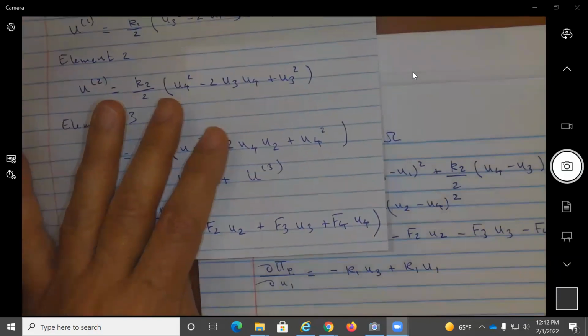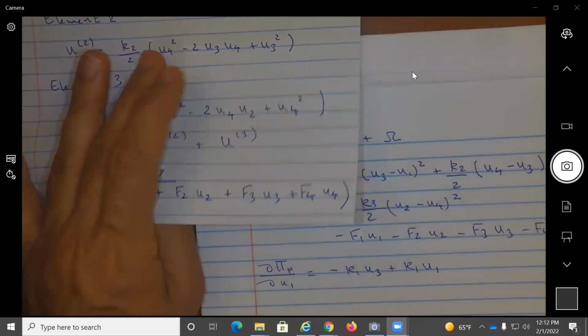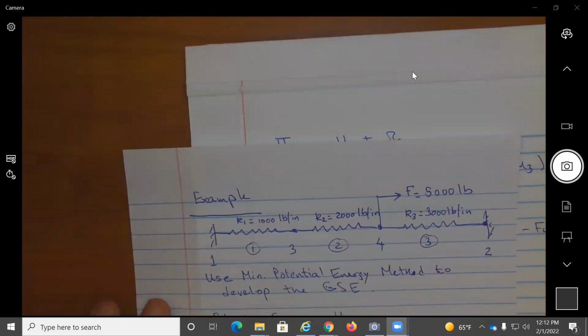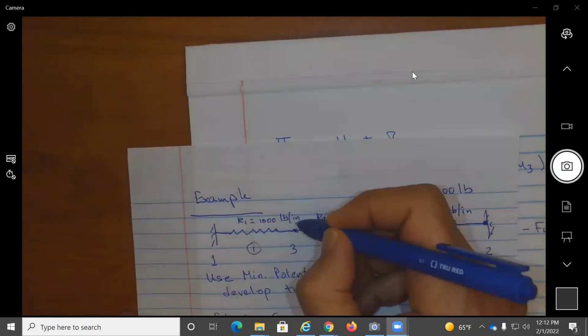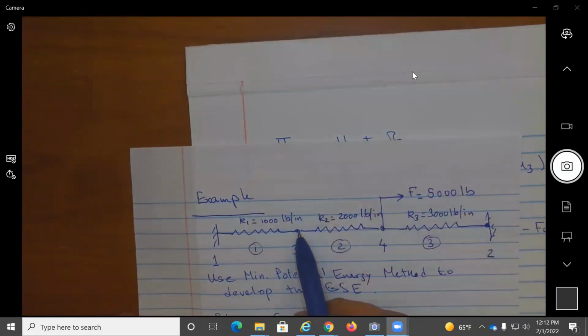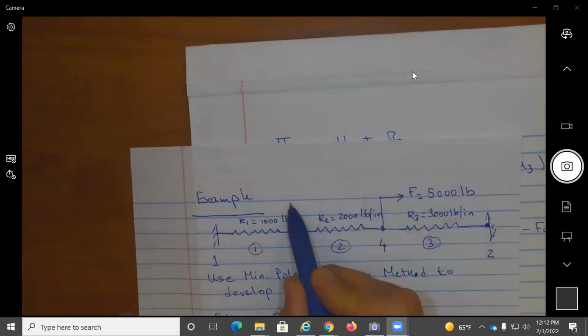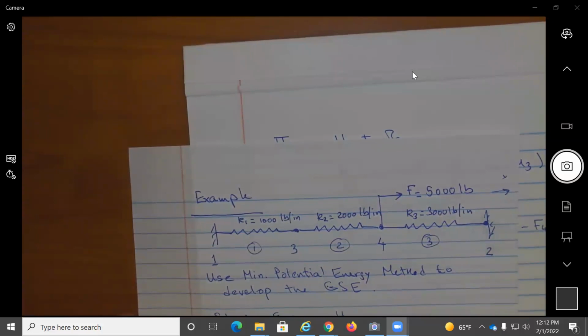Excuse me. I was just thinking, assuming there were forces loaded at other points, while writing the potential energy, you put the minus sign, but assuming the forces were loaded and we know the directions of the forces. Okay, good question. Always, if I'm going to say there is an external force, like clearly there is nothing at 3, but if there was one, I would have made it going in the positive x direction as well. So it's always in the positive x direction. Yeah, we like to do it this way so we don't get confused.